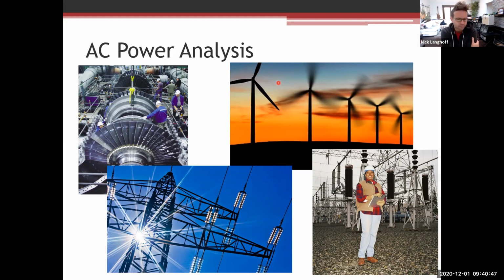And so you lose a little bit of energy as you transmit power over those vast distances. Those power losses are generally called I squared R losses. We look at it in terms of P equals I squared R, and the distance of those power lines is pretty large, so the resistance ends up being big. But if you just drop the current way down, you lose very little power. So if you up the voltage by a factor of 1,000 or 10,000, that's why you might see some of these lines be something like 12 kilovolt lines, 12 kV.